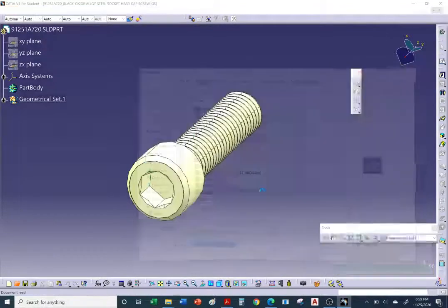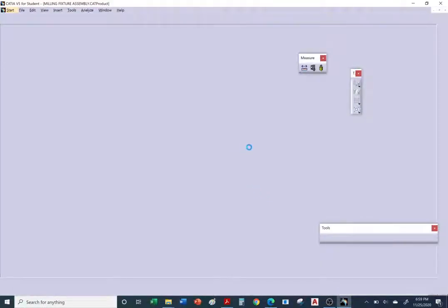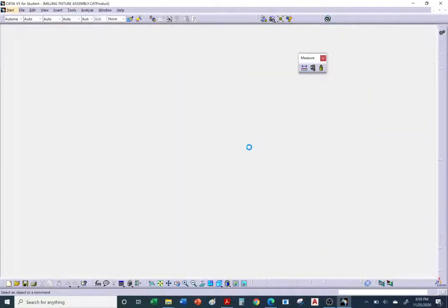I worked at a machine shop under the direction of the supervisor. The supervisor told me what to design. I would do it in CATIA. My supervisor also happened to be the NC programmer. So I would create it in CATIA and then save it as step files or CGRs so they could open it in Mastercam and do the NC programming. A lot of the hardware you're going to see here I downloaded from McMaster and from Carr. I was able to open them as step files and then I saved them as individual CATParts.